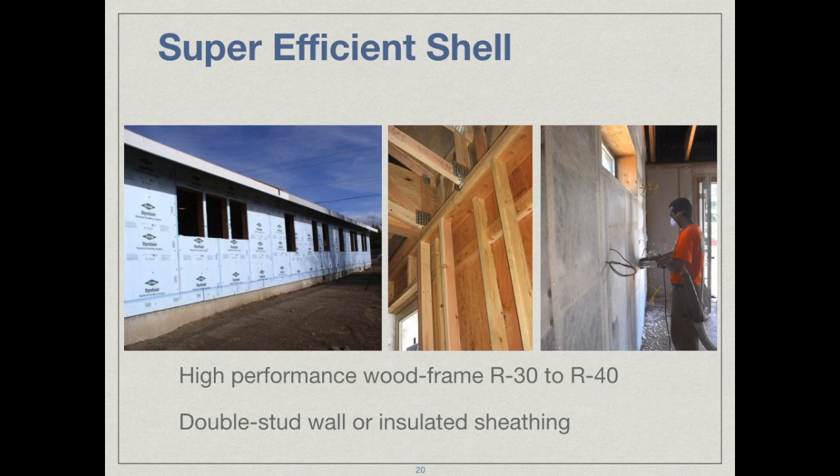If you ask somebody who normally does a double frame wall to do foam on the outside, they probably won't do as good a job as if they had done the method that they're used to. So trust your designer and your builder to do the thing that they are most comfortable with. If you are the designer or builder, stick with the thing that you're most comfortable with and don't try to do something different. In either case, if there is cavity insulation involved, it's better to use blow-in insulation than batt insulation.